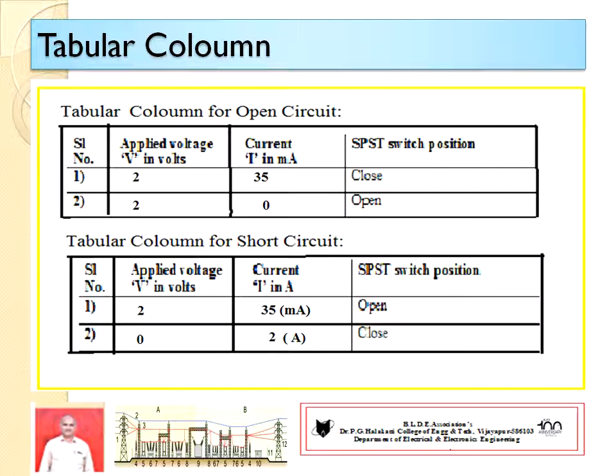Earlier it was 35 milliampere, now you see how much difference. It draws 2 ampere current, but supply voltage is nearly 0. Voltage becomes 0, current becomes maximum in case of short circuit condition. These two are very important faults in electrical circuits.